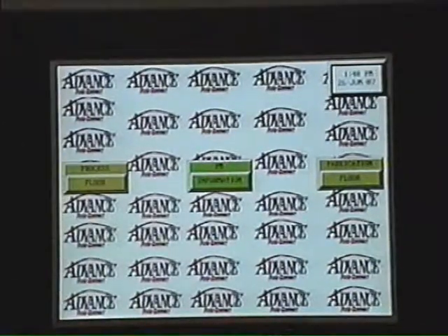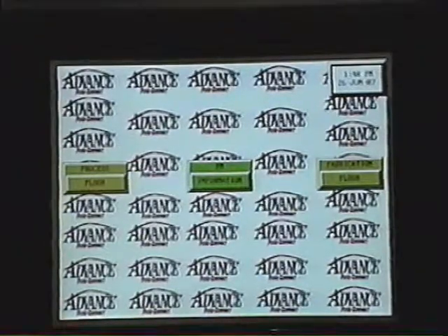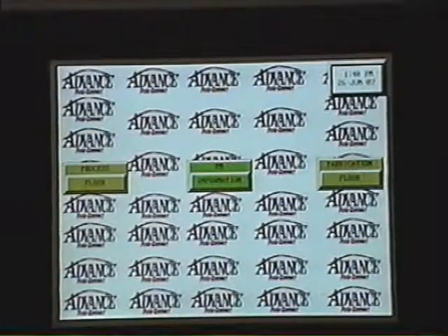This is a video to show the operation of a hydraulic control circuit program for a multiple pump application. It's an energy savings option so that the pumps that are running are controlled by the flow on the floor. The more flow, the more pumps. The lower the demand, the fewer pumps are running.